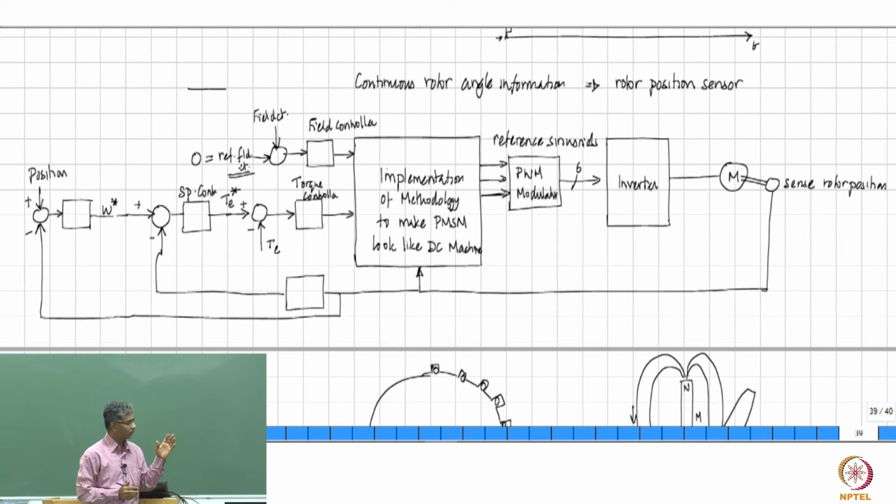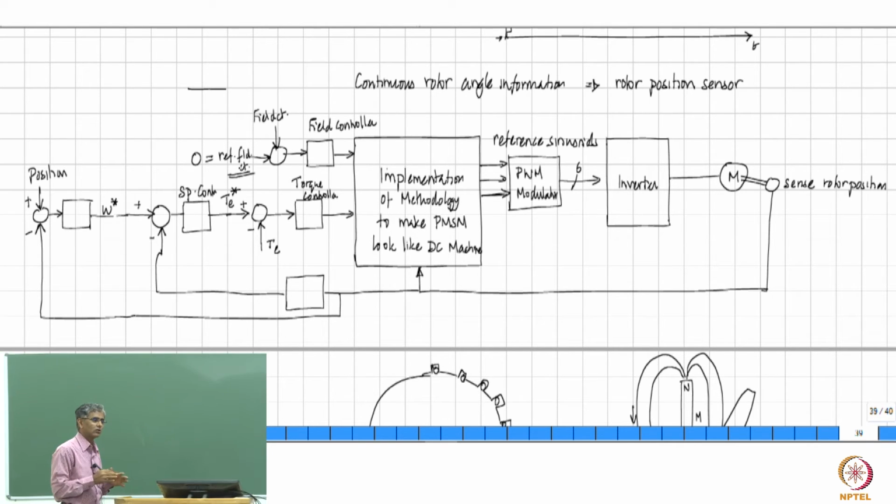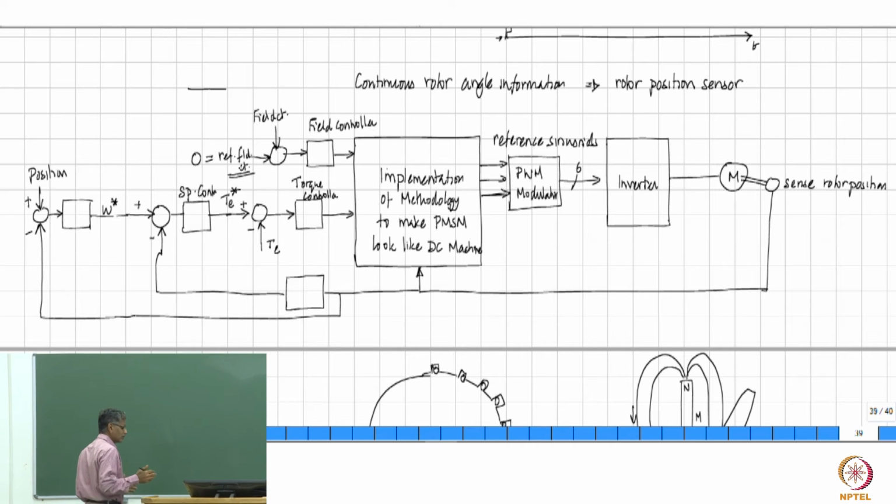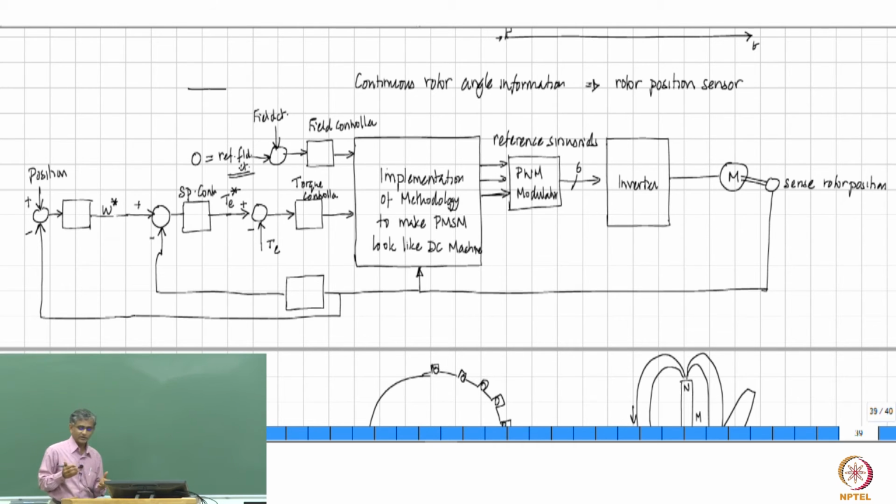right? So you generally say that you don't want to oppose the rotor field, because why? It simply does not make sense, at least at the first look. There is already a magnetic field. Why do you want to diminish that magnetic field and send extra current to generate that required amount of electromagnetic torque? So you leave that field as it is and then do it.